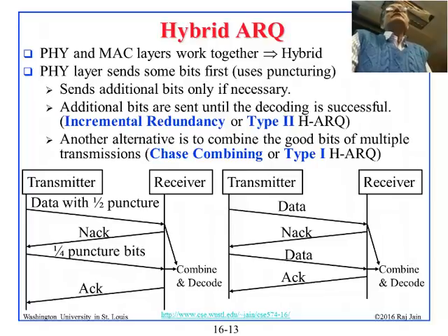Just another question. With the retransmission of the bad bits in the hybrid ARQ, does that require a whole other frame? Basically what will happen is these bits will be sent to the same user, and it will indicate that this is the HARQ retransmission of that previous frame that was there. It's just a smaller payload than it would be. Yeah, right.